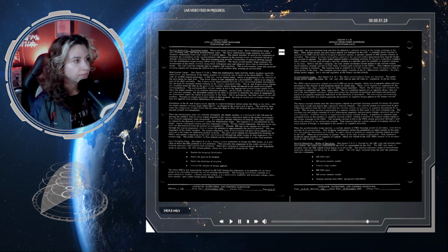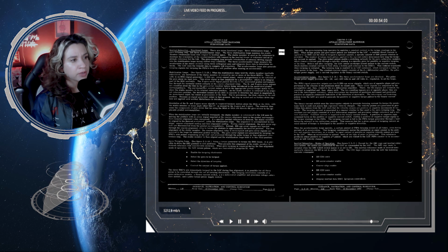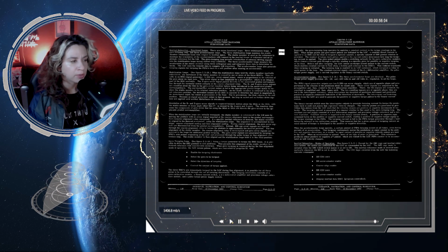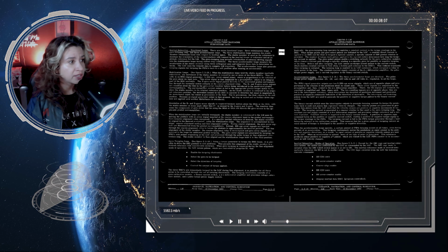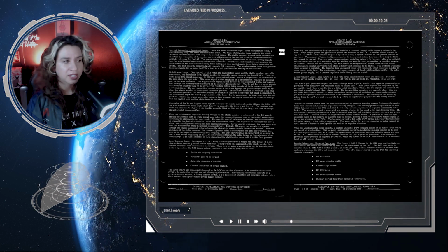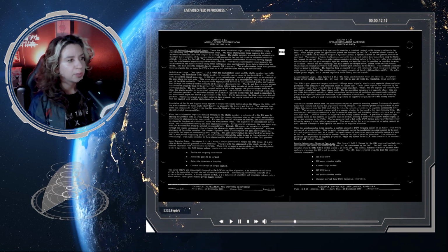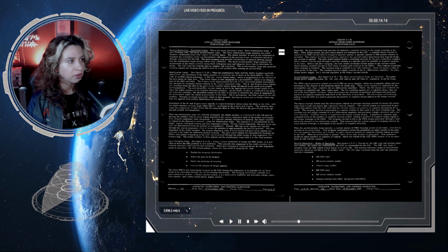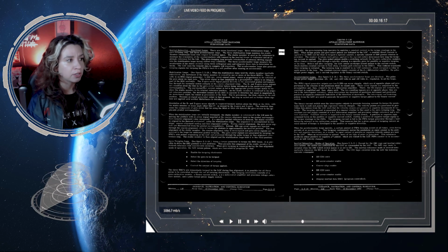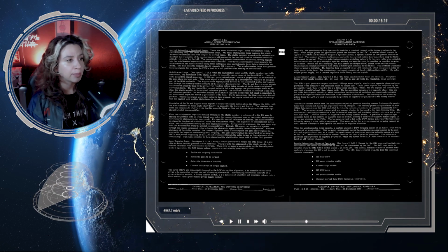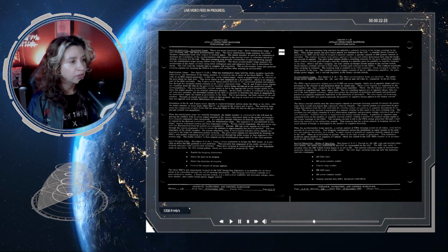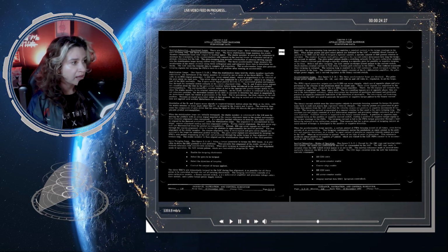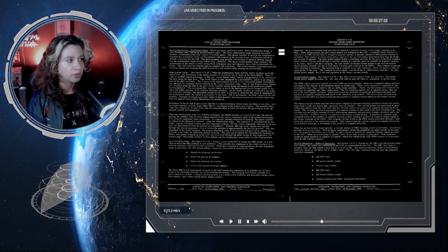Where was I? As the stable member is returned to the original position, the result is precession of the float. Due to the precession, the float returns to its null position. Because no signal generator output is then present, the loop is nullified, and no further drive signals are applied until another disturbance is introduced.